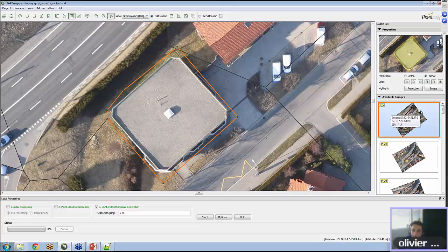When you select another cell, if you are not satisfied with the projection that you have achieved, you can navigate and check other ones to find one that fits the perpendicular projection better. With this example, this cell is quite good because there was one image that was more or less over the object. And that shows how important the overlap can be for editing the orthomosaic.